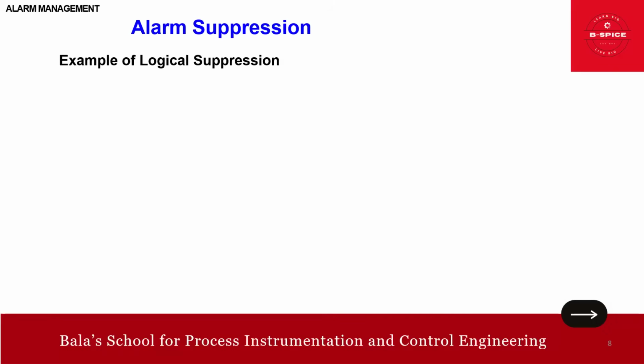Then eclipsing is nothing but, for example, there are successive alarm limits, thresholds basically. For example, high and low. The second level of the alarm, meaning high priority, the most urgent one, can eclipse the first alarm, the less urgent one, the low priority alarm.